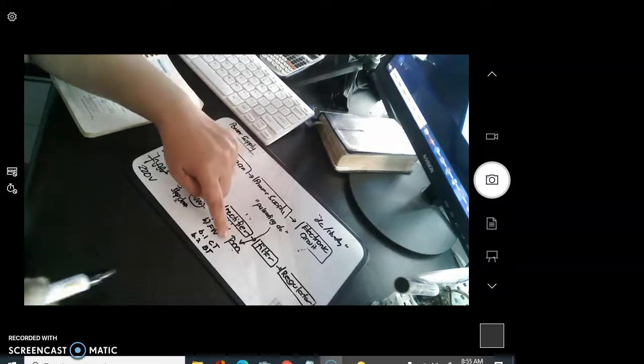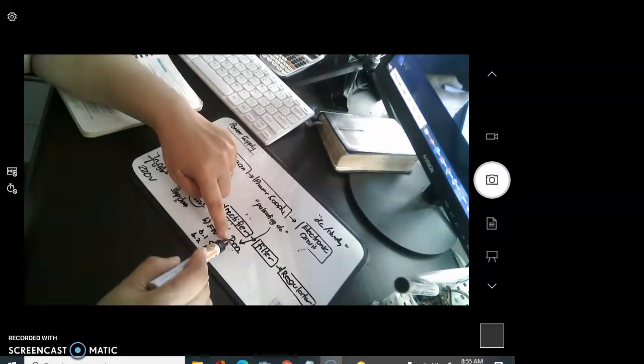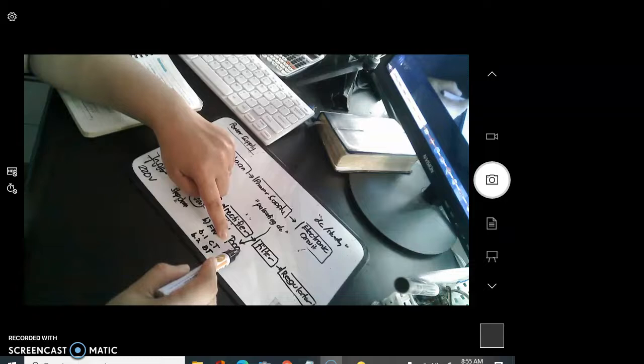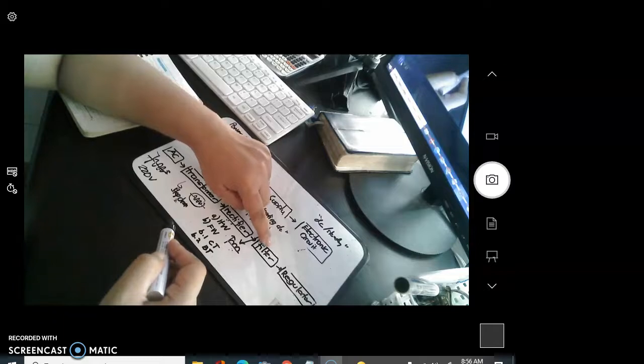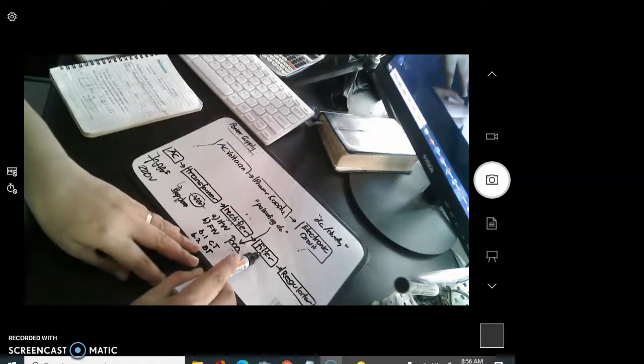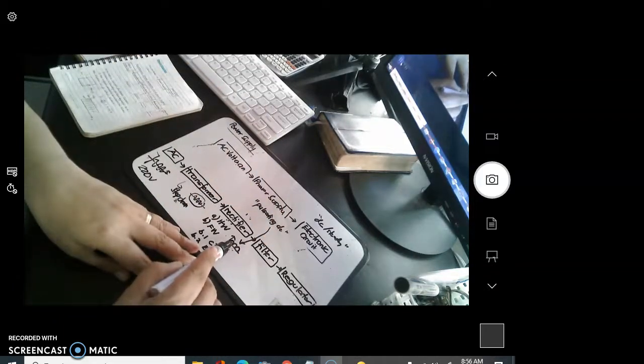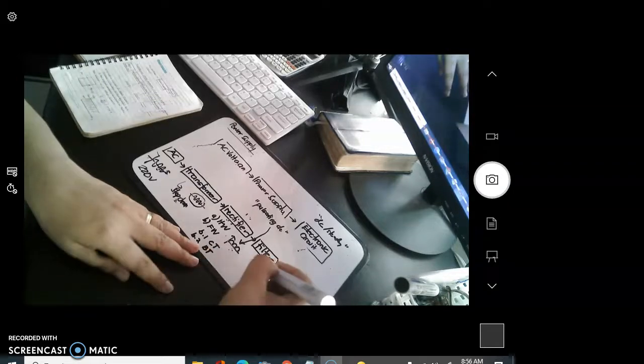Why pulsating DC? As you can see, there is a value that is low and there is a value that is high, another value that is low, another value that is high, which is pulsating. It is not yet a steady direct current, but the values are all positive, therefore this is already a direct current. Why? Because all values are positive, there are no alternating values. Now, to improve this signal, the signal must pass to another circuit, and that is what is known as the filter circuit.